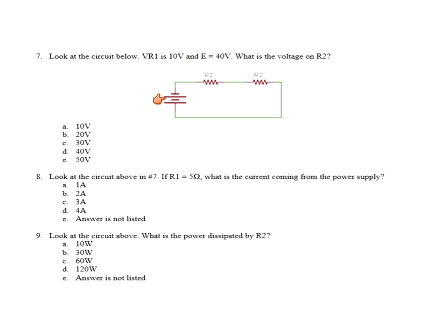The total voltage is 40. The voltage on R1 is 10. What must be the voltage on R2? Well, we know that these two voltages have to add up to the total. So if this is 40, I have 10 on R1, and then I have how much here? Well, 40 minus 10, that must be 30 volts. So my answer for that one would be 30 volts.